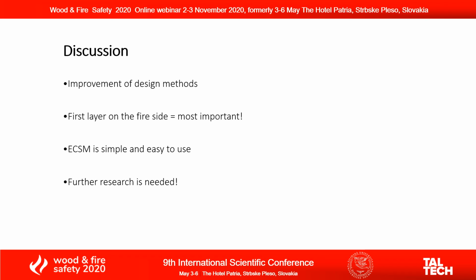That means that, for example, the ability of a gypsum board to stay in place for a long time has a great influence on the total result. The design methods presented here are able to consider that, along with the contribution of the insulation materials. The effective cross-sections are simple to use in further load-bearing analysis.